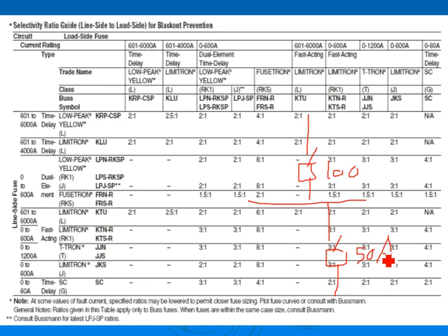The rule of thumb for circuit breakers, I used to say 50, but to get a better coordination, probably a fourth. So if that was a circuit breaker, to get a good coordination, if that was 100 amp, here's a circuit breaker coming in here, circuit breaker coming out. So 25 amp. That will give you a good coordination. If your feeder is 100 amp, the maximum that you can pull with a good coordination without worrying about it is 25 amps. And how far do you take that? All the way down to the smallest?